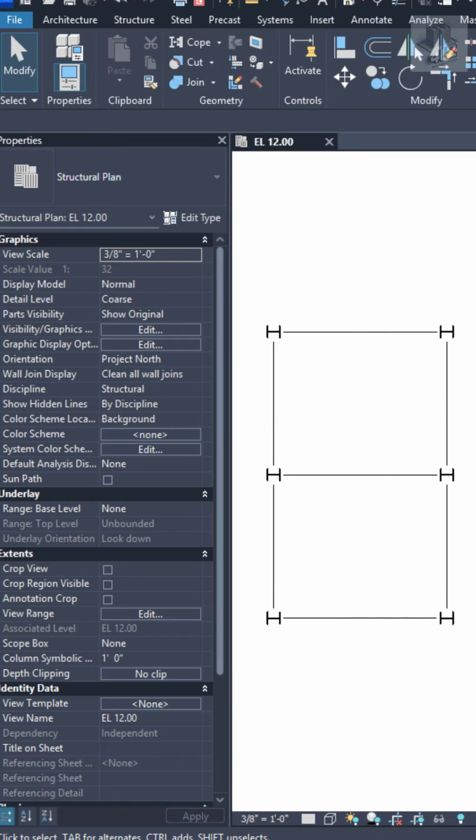In this video, I'm going to walk through the Revit Bracing tool, an efficient method for placing vertical bracing between columns and horizontal steel members. While you can technically place bracing using the standard beam tool, only the bracing tool gives you access to the proper structural usages for vertical bracing and kicker bracing. It also unlocks several useful control settings you'd miss out on otherwise.